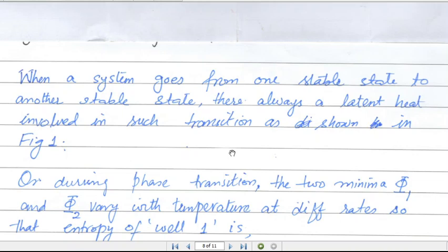As we discussed at the start of this lecture in figure 1, whenever you heat a piece of ice, the temperature of the ice will increase, and when it reaches 0 degrees Celsius, the temperature stops increasing for a certain period of time. That is the period when the system absorbs heat from some external source. And that absorbed heat is basically the latent heat of fusion, or latent heat of vaporization in the case of a liquid gaseous transition. So whenever there is a phase transition, as we already discussed, there is an abrupt change in different properties of the system.